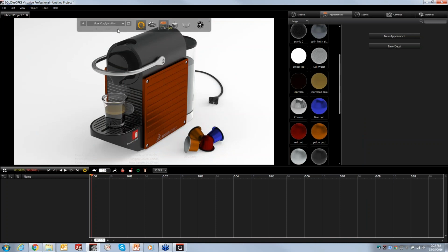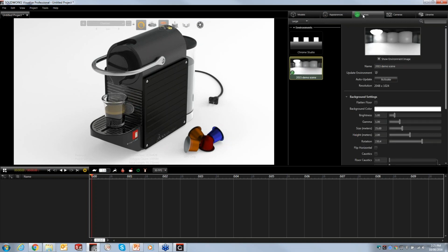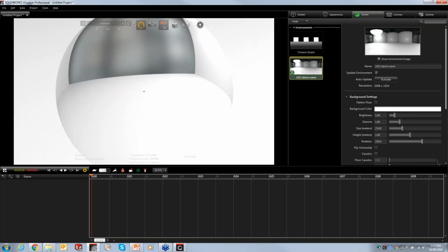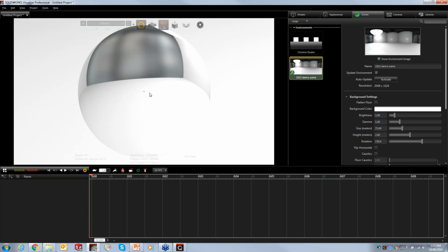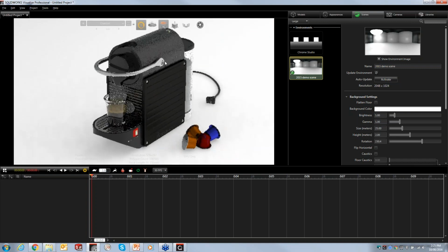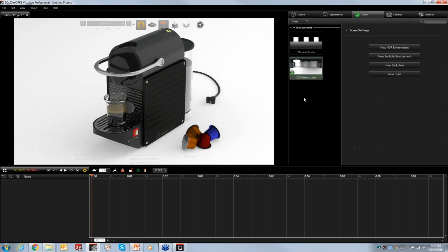Okay, so let's go ahead and choose the charcoal. This is the one we're pretty pleased with. We're going to carry on working just with the fast rendering option because it works quite well for the demonstration. And we're going to move ahead and look at the next tab, which is the scenes. So in SolidWorks Visualize, if I zoom right out, we can see the HDR environment actually pulled into my model, and we can manipulate, work with it, or create new ones using HDR Light Studio directly inside of here.